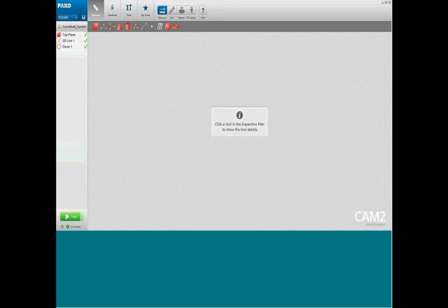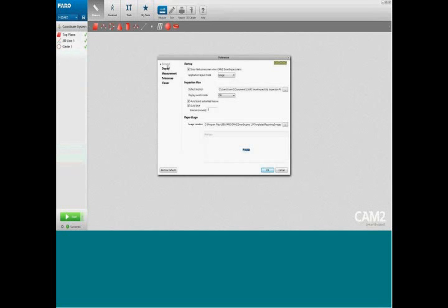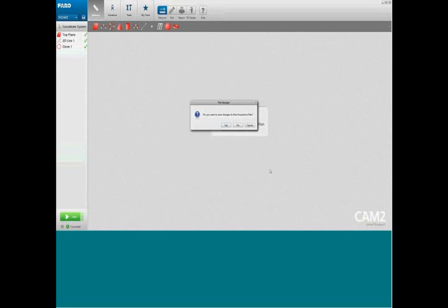As a majority of you are familiar with CAM2 Gauge, I'll now move on to SmartInspect Pro. We switch between Basic and Pro via the preferences in the Home menu. We go to the Home menu, we choose Preferences. Under the General options, we have Application Layout Mode. We now switch this from Image to 3D. The software will reboot and restart when I click OK.